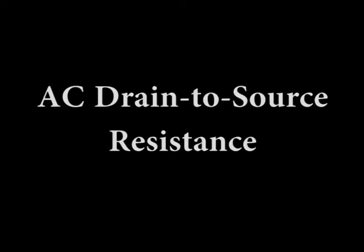AC drain to source resistance. You learnt from the drain characteristic curve that above pinch off the drain current is relatively constant over a range of drain to source voltages. Therefore, a large change in VDS produces only a very small change in ID.